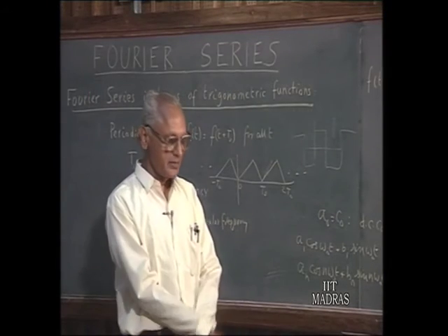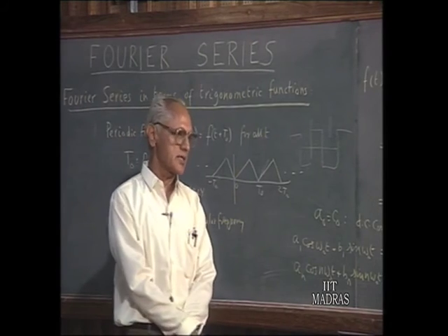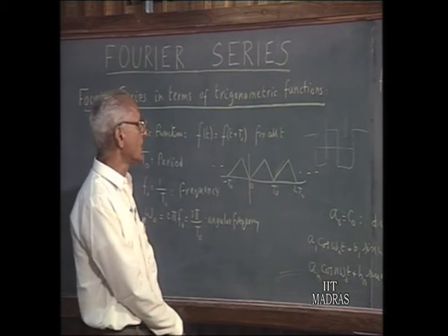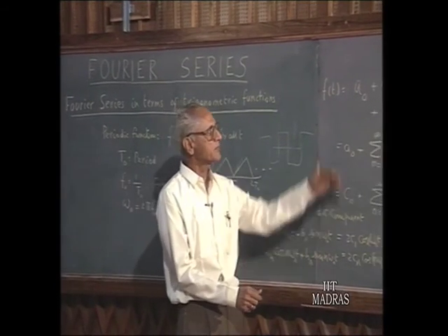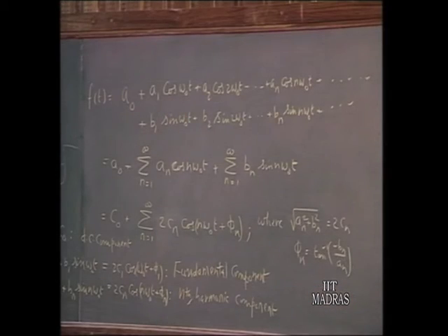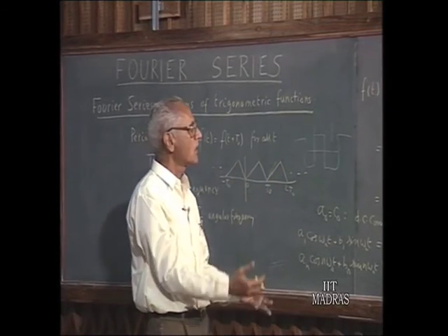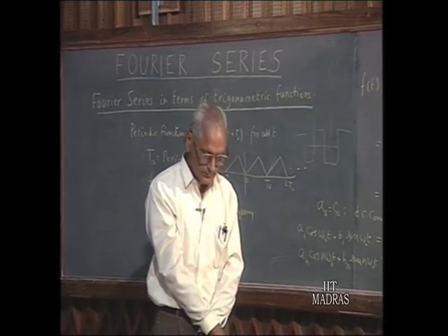That is the basic idea of the Fourier series as far as circuit analysis or system analysis is concerned. A given composite periodic function can be resolved in terms of various sinusoids, and we know if there is a sinusoidal driving force, we can find out easily the steady state response. For each sinusoid, we find the response and add all these responses to get the total response. So it is in this context that the question arises: if we have an infinite number of terms, how are we going to grapple with this?